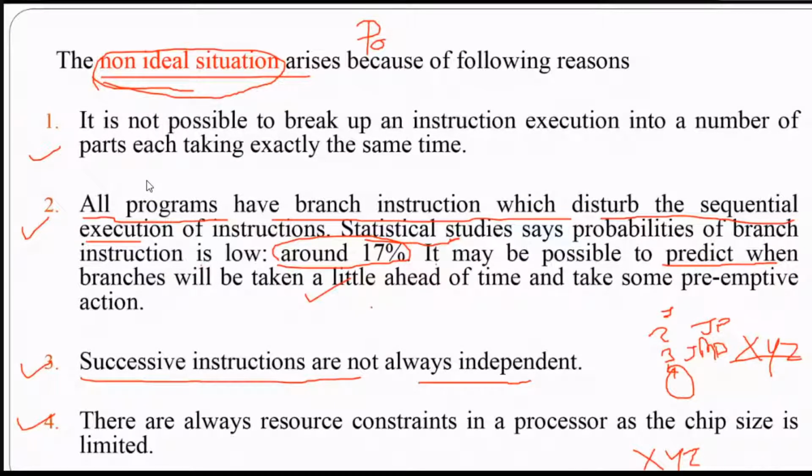Suppose यहाँ पे मैंने लिखा हुआ है add. First instruction is add R1, R2, R3. We will see lots of examples हम यहाँ पे study करेंगे. Suppose ये instruction है, तो इसमें हमारा result कहाँ पे store हो रहा है? So our result is stored in R1 register. And same way, in the next instruction itself, we are directly taking this R1 as one of the sources. Perform subtraction between R5 and R1 and store result in R6.